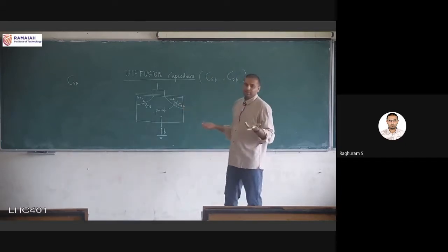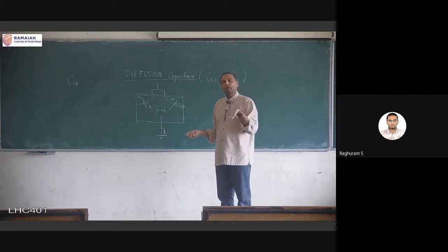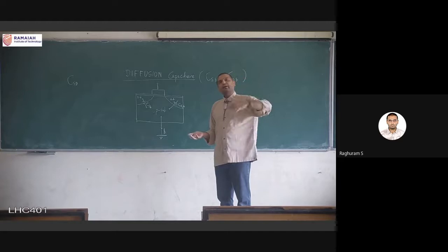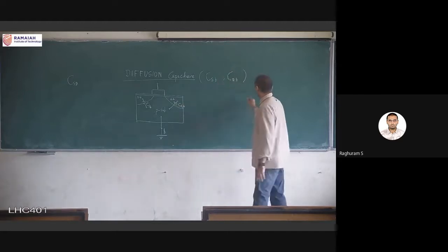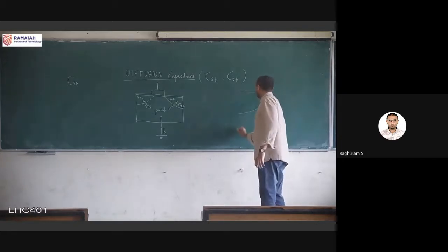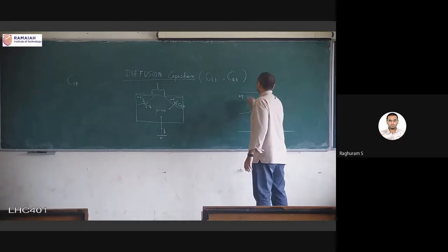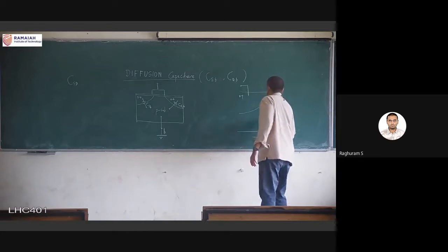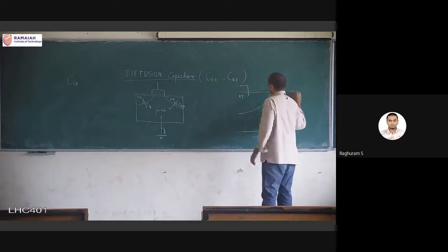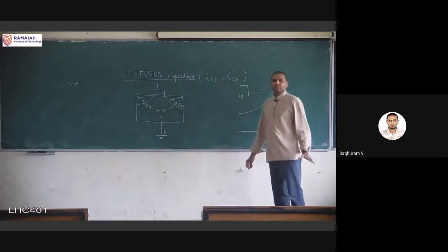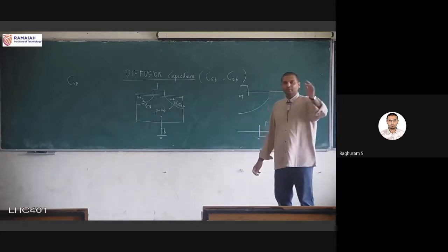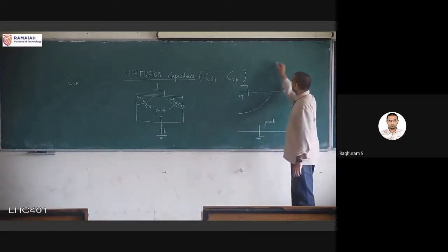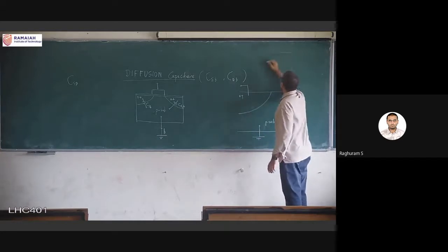So in this case, we didn't make the PN junction separately; we put the n-type doping on top of the p-type substrate, but still it is a region where n and p are touching each other, so automatically it is a PN junction. So if you want, I can draw it like that also. Right, this is my PN junction. I'm only looking at the junction part here, and I'm trying to explain why there is a capacitance. So we understand that there are two parallel plates, but also because of this particular connection, this PN junction.